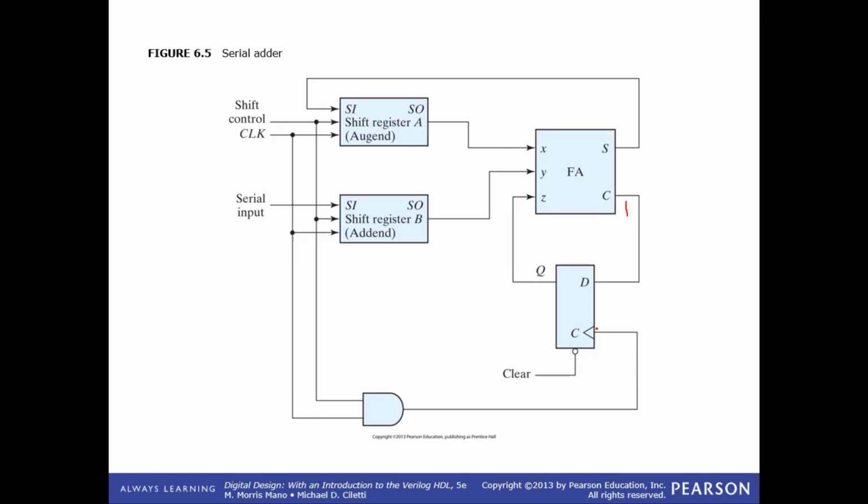And how do we do that? We do that with the help of the second positive edge of the clock. When the next positive edge of the clock will come, this 1 from the D would come to the Q and to the Z. So this one would appear over here in the next sum, which is exactly the thing that we did in 1001 and 0001. Now see, if we have this 1 1 sum equal to 0, the carry needed to be added to the second sum, which is over here.